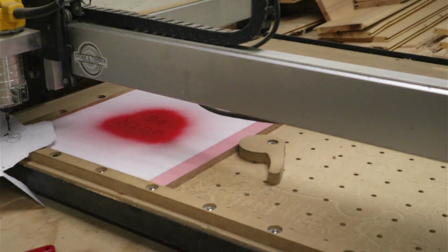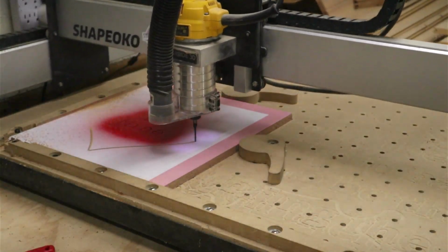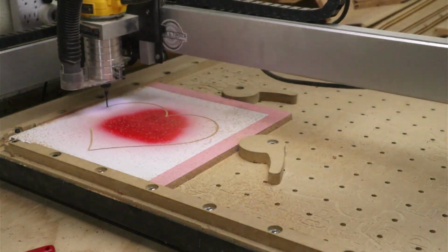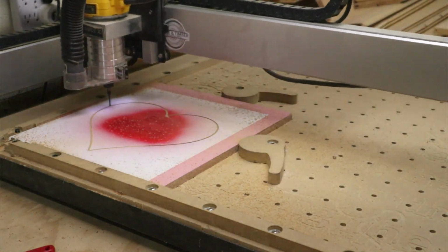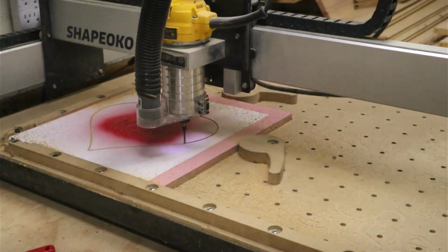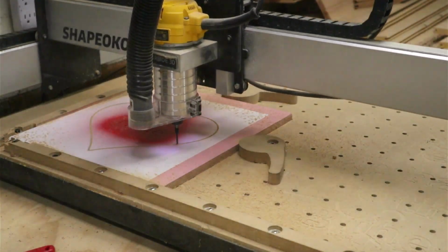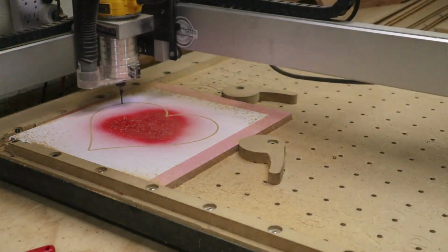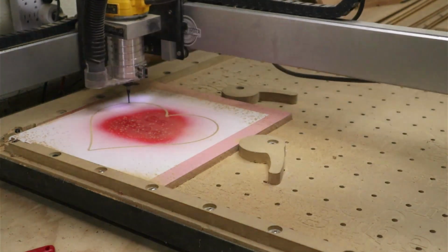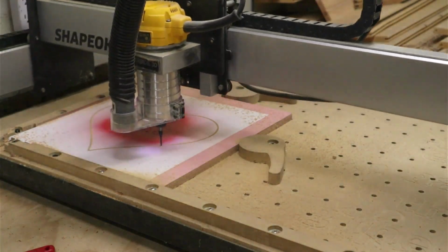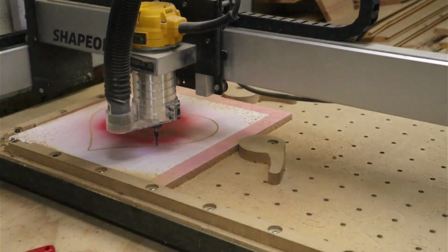If it doesn't cut the whole way through, it is going to be extra work afterwards, because then I have to cut it out with a bandsaw or something to actually break through that back side. And I have had some problems with that. I don't know if it's my estimate of how thick the actual workpiece is, but it never seems to quite go through. And I try to be extra careful not to cut into that spoil board underneath, but lately I've been trying to go just a little bit deeper than I think necessary, just to try to make sure I punch through the back side of that workpiece.